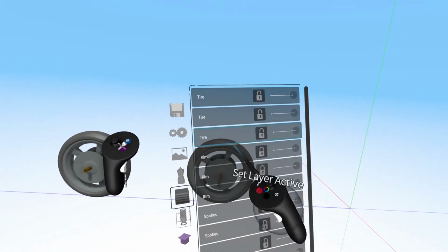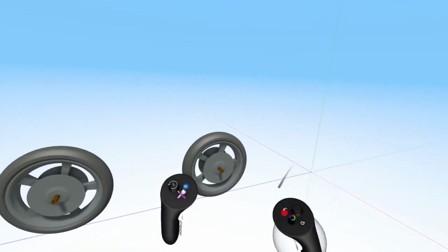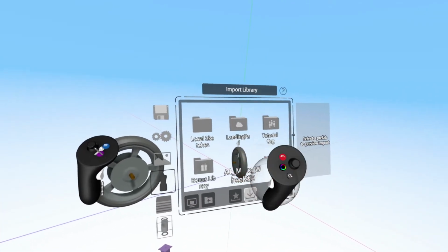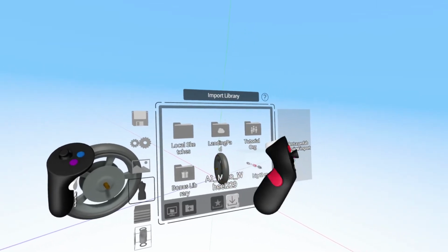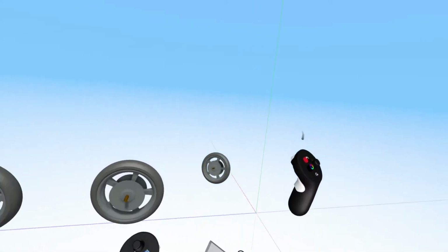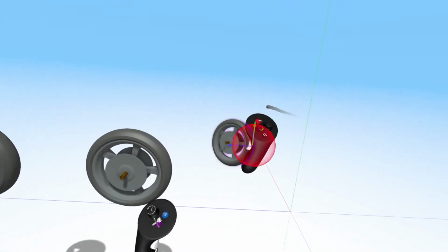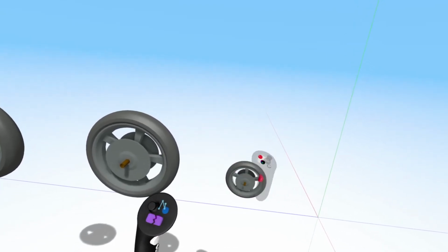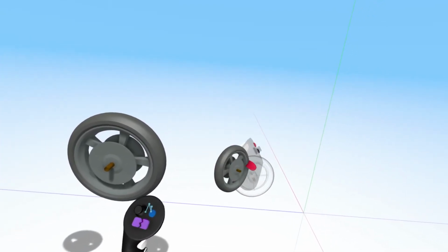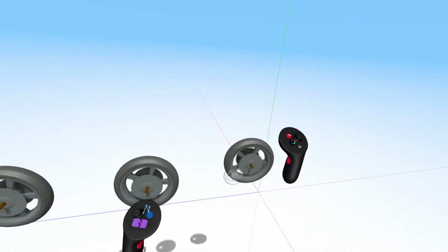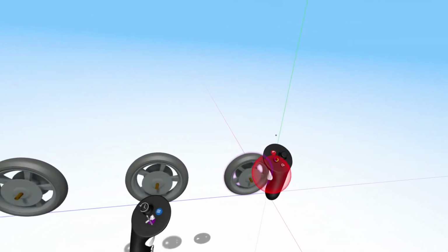The second method is to grab and place the file in your scene manually. Select the file using the grab sphere, and then grab it using the grab trigger. Then drag it into the scene and let go of the grab trigger. Placing the file into your scene using this method is quick and easy. However, location and scale data is lost. In addition, for files created in Gravity Sketch, layer structure is also lost, meaning that when you use this method, the objects will be a simple group of objects on a single layer.